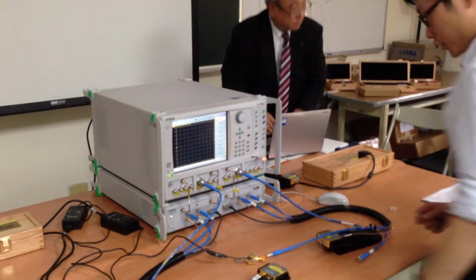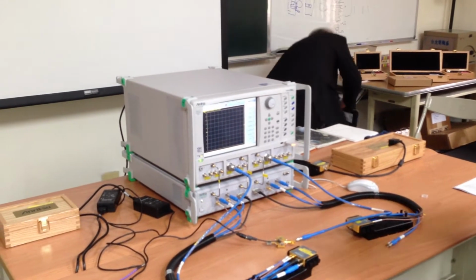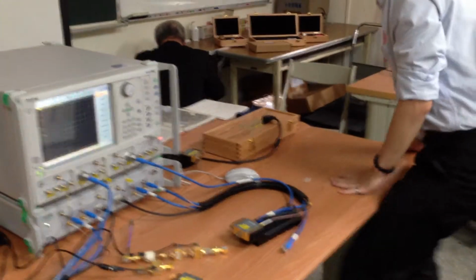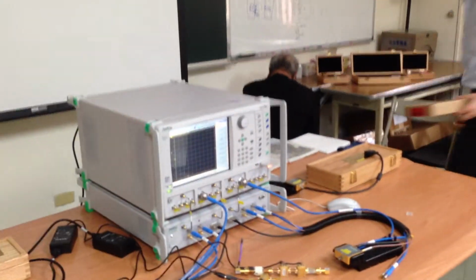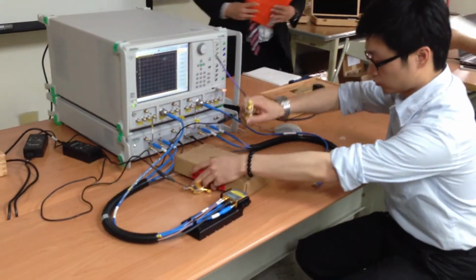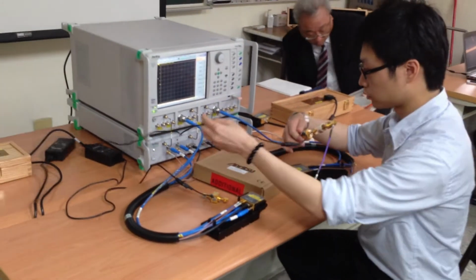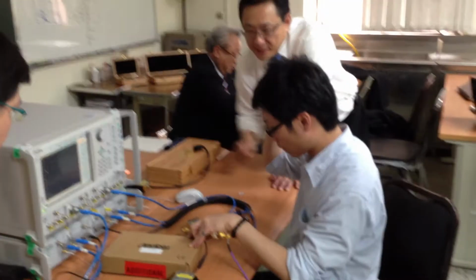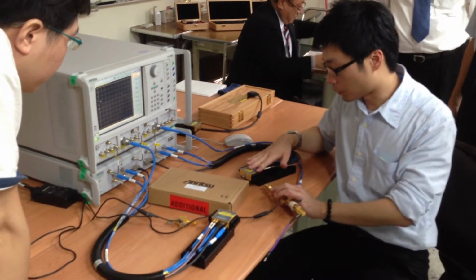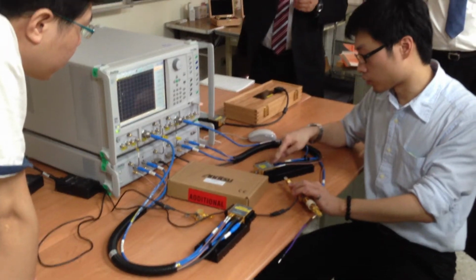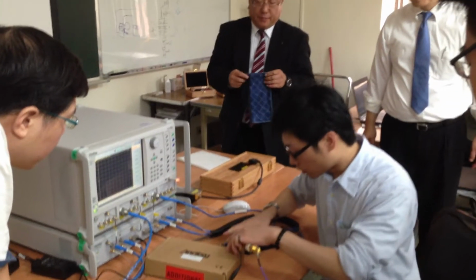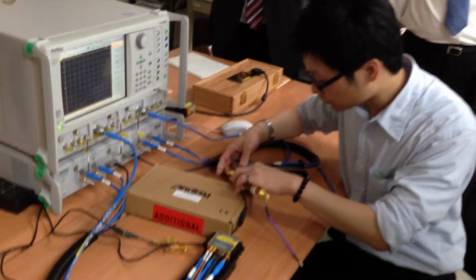So they are ready to see the demonstration. Connect the receiver module. The receiver module only needs the local and test connected. From the VNA, the RF cable does not need to be connected, and the reference cable does not need to be connected. Then next, connect the common side receiver to our receiver module.